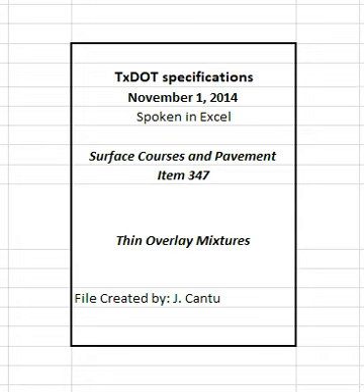4.4.2.1.18 Requesting referee testing. Use referee testing, if needed, in accordance with Section 347.4.9.1, referee testing, to resolve testing differences with the engineer. Table 8. Operational tolerances. See table in specifications. 1. The contractor may request referee testing only when values exceed these tolerances. 2. When within these tolerances, mixture production gradations may fall outside the master grading limits, however, the percent passing the number 200 will be considered out of tolerance when outside the master grading limits.